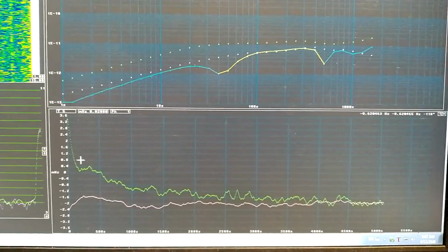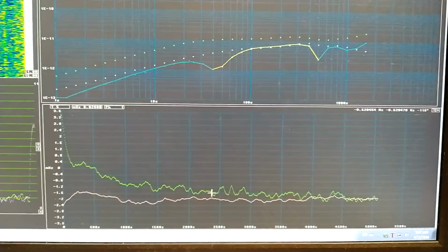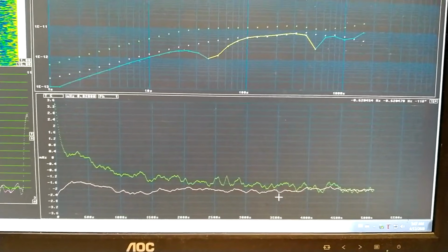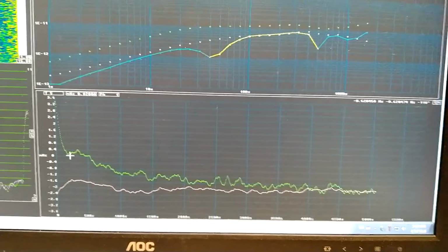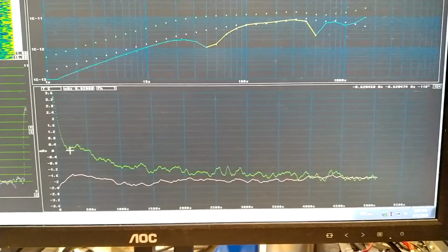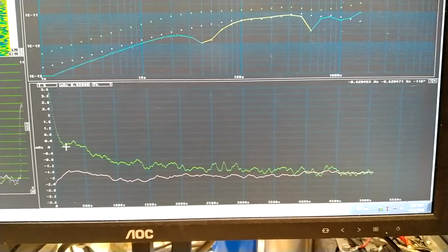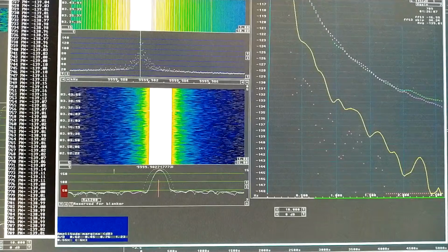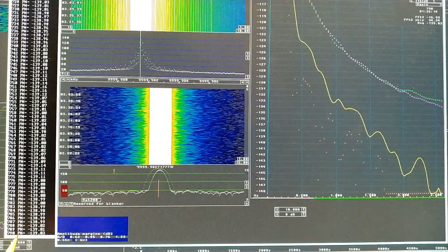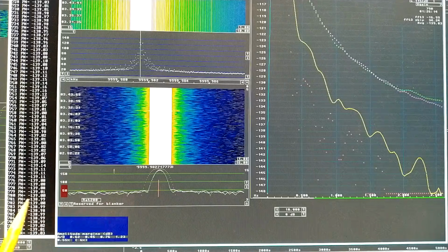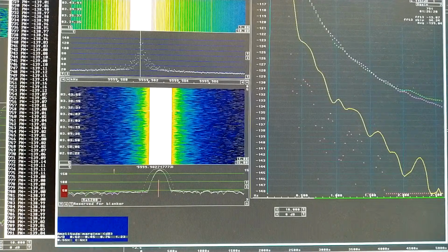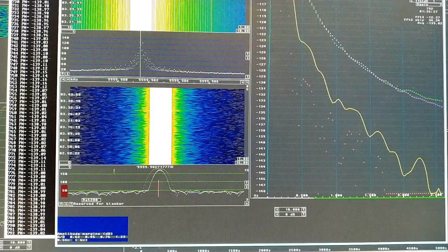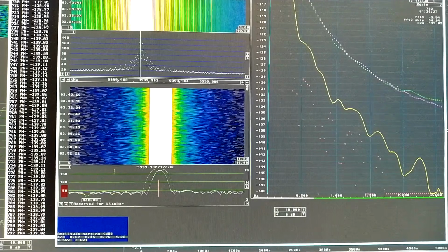You can see the long time it takes for the two oscillators to reach the same frequency because of the very long time constant for the PLL. I will allow this to run for a long time now, looking for the stability of the average phase noise. There could be noise bursts from the channel 1 oscillator, I don't know that yet. So I will make a time-lapse video so I can check afterwards whether there have been any events.